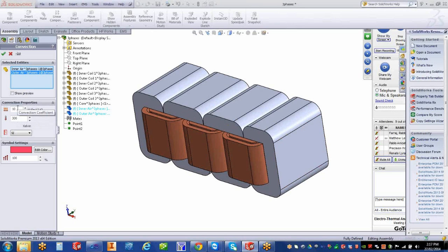Now let's talk about the limitation here. This is not going to replace your SolidWorks simulation, where you have a really powerful thermal program or fluid there. We assume that the convection coefficient is constant for that surrounding liquid or material.